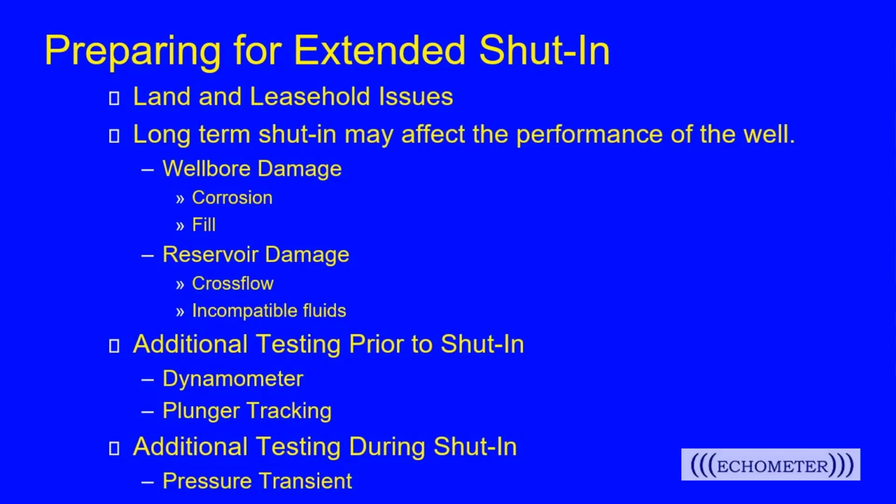Also, long-term shut-ins may affect the performance of the well. We may have some wellbore damage. It could be that we have some corrosion going on if we have this well shut in for a long period of time and we're not using the proper corrosion inhibitors. It may be that we have some fill, perhaps from frac sand, and especially since we're not producing the well, that fill may be accumulating at the bottom of the well.